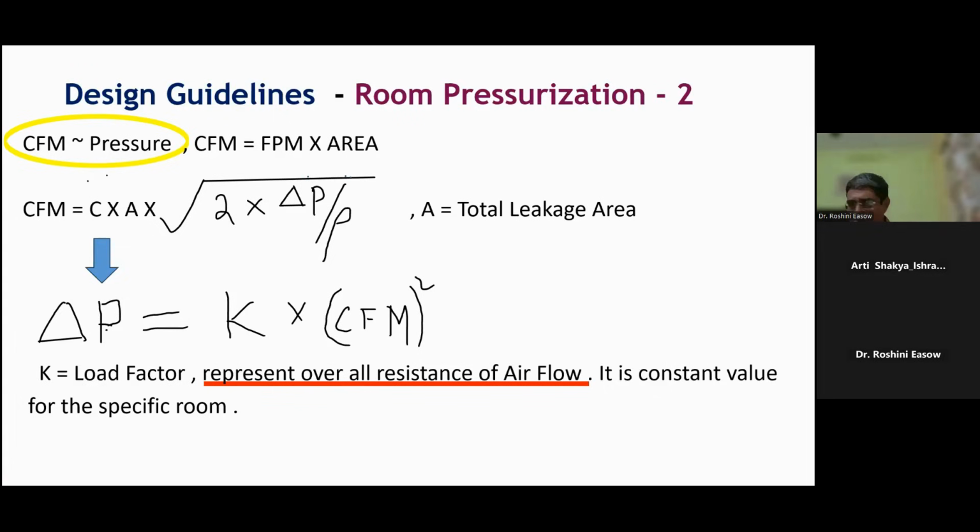When air is moving, there are plenty of instruments and gadgets in a surgery room. Unless you consider this K factor of a surgery room, your design CFM will not hold the same. Definitely there will be a loss. So the K factor is to be added, and it depends on the consultant who is designing. It is defined from room to room. But I am particularly telling you about the surgery room. Those who have been to a surgery room know how many gadgets are there. So the K factor is very important.